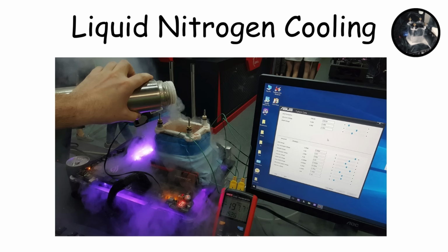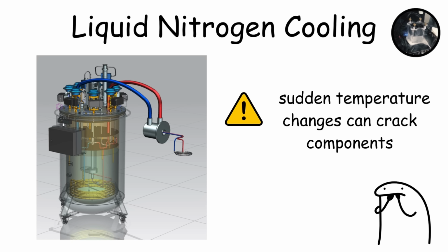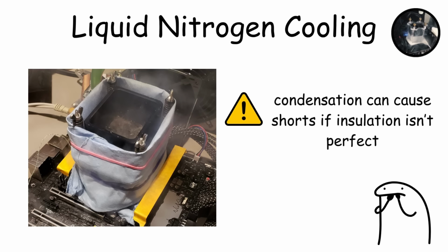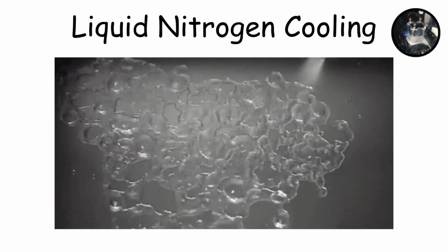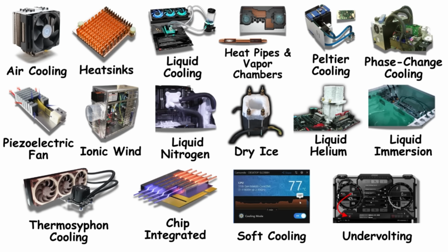It's silent, but short-lived because nitrogen boils off and must be constantly refilled. It's risky too, as sudden temperature changes can crack components and condensation can cause shorts if insulation isn't perfect. Liquid nitrogen cooling is strictly for benchmarking and competitive overclocking. It's not practical, it's not safe for daily use, but in raw performance, nothing else comes close.